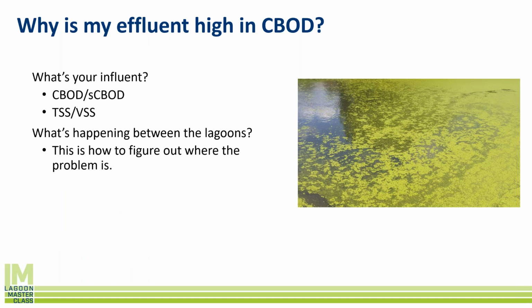And the reason was because the collection system was short. Now the operator wasn't doing anything wrong before. He had been reporting 400 CBOD, but basically the way the plant was set up, he wasn't able to sample properly. And so when the plant was designed, it was actually too small based on what the CBOD readings coming into the facility actually were.